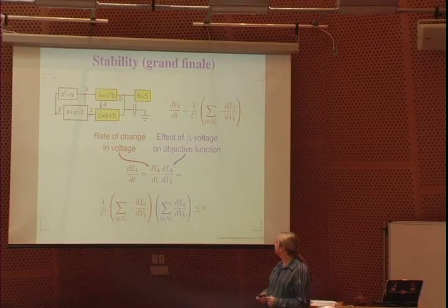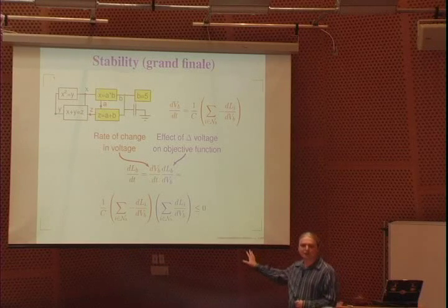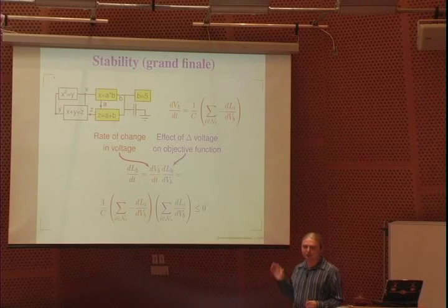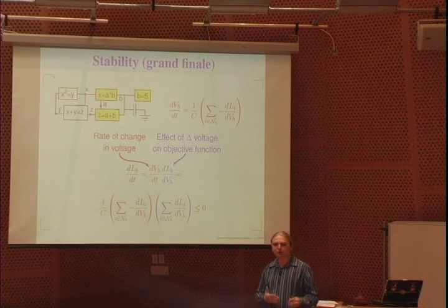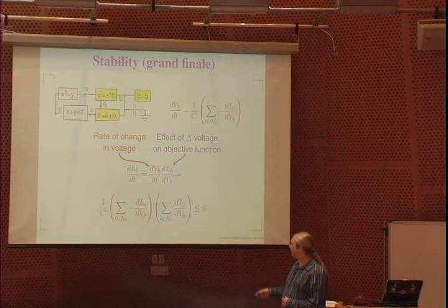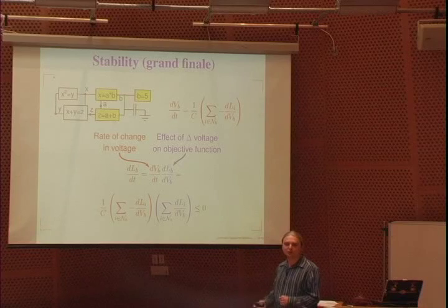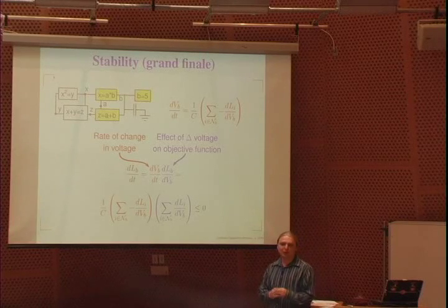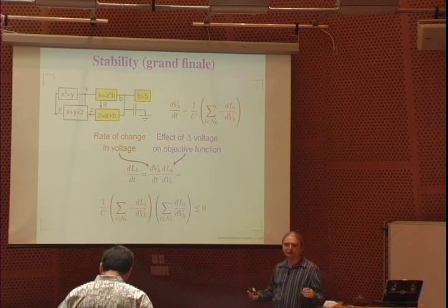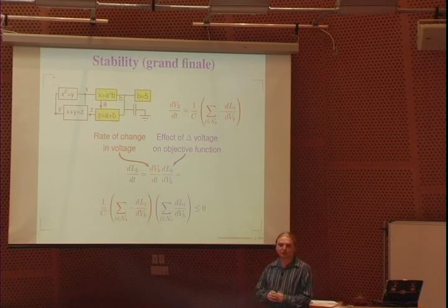Oh, yeah, I should mention that for stability, this argument shows stability in the ideal case. If you're looking at a real system, it won't behave exactly like the ideal case. There is a robust stability argument that I won't present. If somebody has a question, I can present it at the end. In addition to that, the way you guarantee high frequency stability is by making these capacitors very large. This argument at low frequencies doesn't depend on those capacitor values at all, and high frequency stability you can get by a variant of the small gain theorem. So if you make those capacitors as large as you want, you can make the high frequency gain as small as you want, and that guarantees high frequency stability.